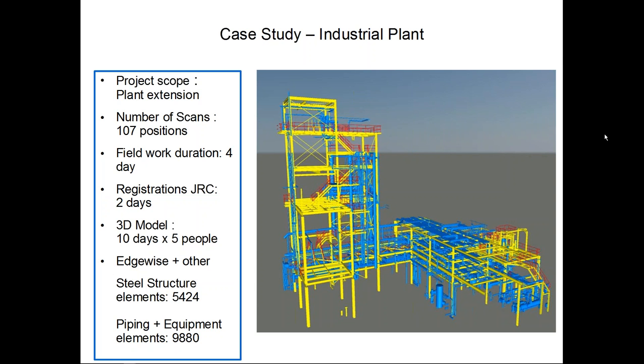We can directly start scanning, and at any time during this process, the surveyor can measure 4 targets for us for georeferencing. For scan-to-scan registration, we just use the scan data itself.